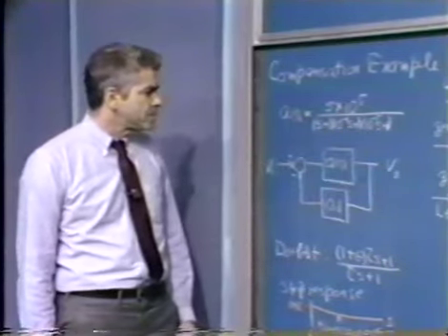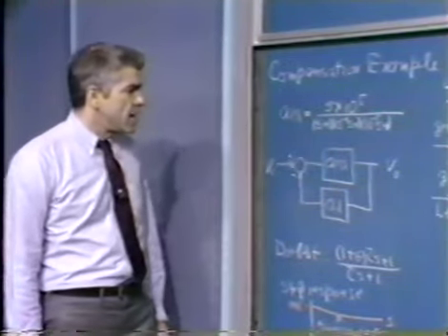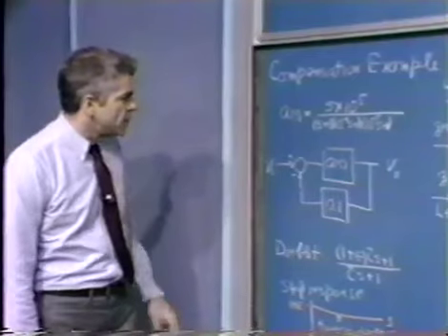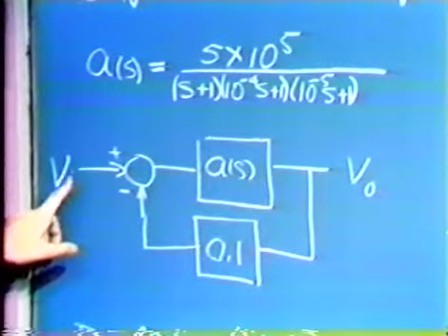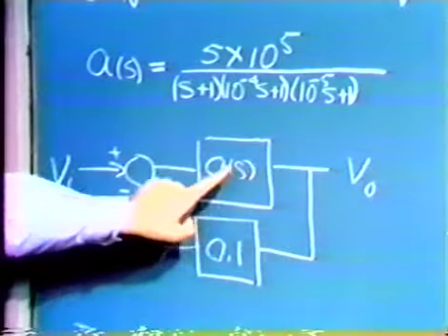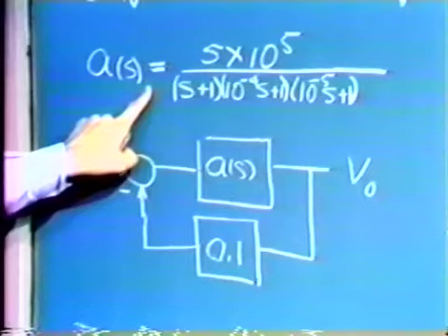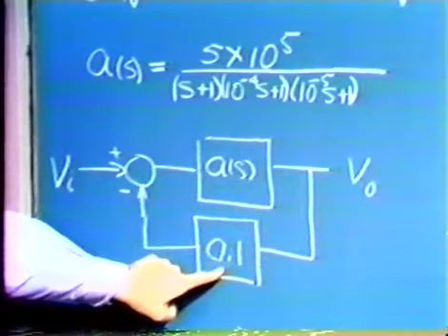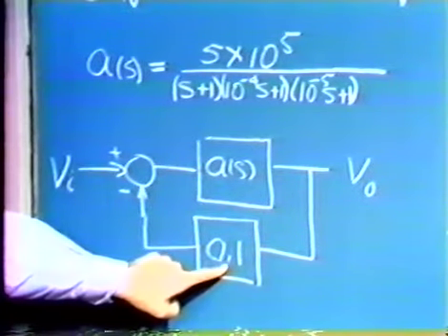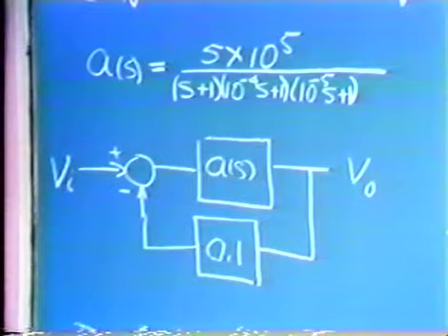If we take our operational amplifier and connect it in the non-inverting gain of 10 configuration, we get a loop that's indicated by the block diagram here. The input, the output, the open loop transfer function of the operational amplifier, the quantity that we've introduced earlier. And then in this particular system, we have a feedback transfer function F equal to 1/10, representing the attenuation associated with the 9R versus R valued resistor.